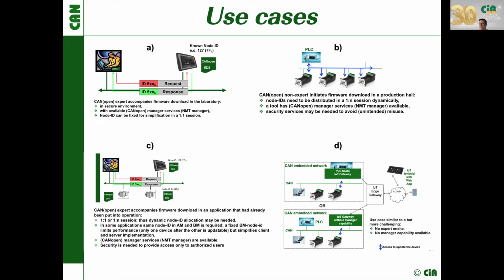And a little bit more complex is if I want to do the firmware update already in the field. So I have to differentiate between devices. I have to put devices or intended devices into this bootloader mode and to perform the update. So typically in a one-to-one session, I may have manager services depending if I come via a tool or via the host controller. And of course, I need some security mechanisms to authenticate myself to the system, to the device, that I'm the intended person to perform now this update of the firmware at this device already installed in the field.